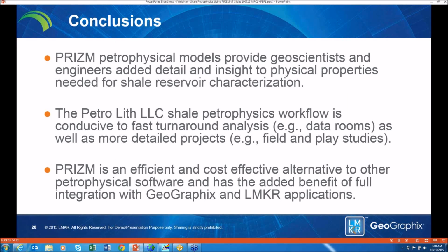All the while the target points were being digitized in the cross-section, Pro3D was updating the well bore view display in real time. If the plan is modified in the vertical section view or in Well Planner, the 3D view automatically updates with the latest data. The 3D scene can be particularly useful for preliminary anti-collision detection.